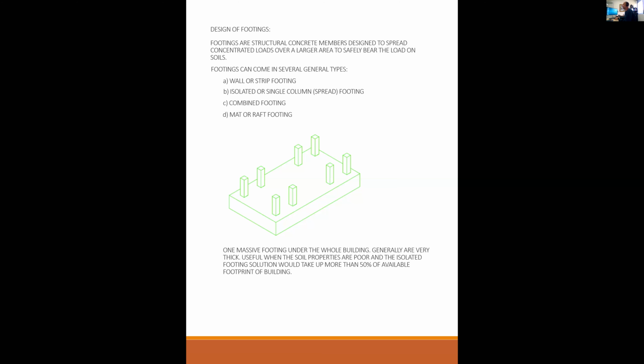It's not really structural. Whereas a mat foundation is usually more like 18 to 24 to 36 inches deep, and it's taking structural loads from columns like my illustration here. It's designed using 318 because you've got to take those high point loads and distribute them out with bending and shear in every direction. So it's really a different thing.